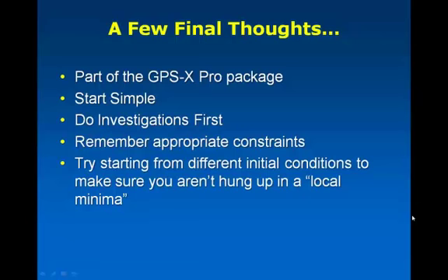Always good to do a few investigations first to make sure that the parameters you're trying to optimize actually do make an effect in your model the way that you hope they will. I suggest that you put in appropriate constraints for all of the values that you're putting into the optimizer control, rather than just blindly looking at the math. If you put an SRT set point in there, you want to put it in a range that's appropriate for whatever your plant's been designed for, so that it doesn't go outside the bounds of reality.